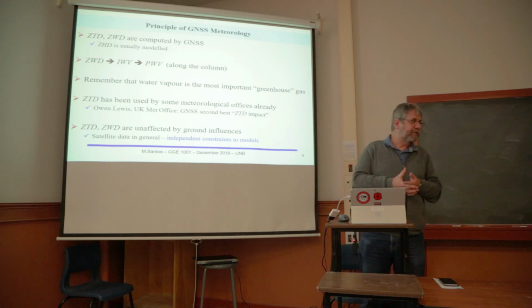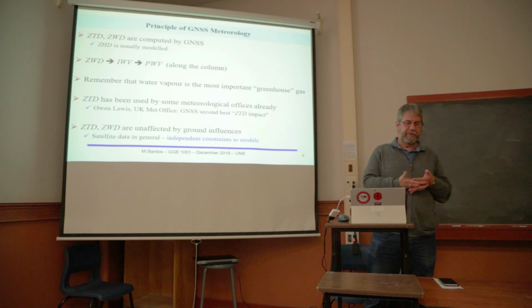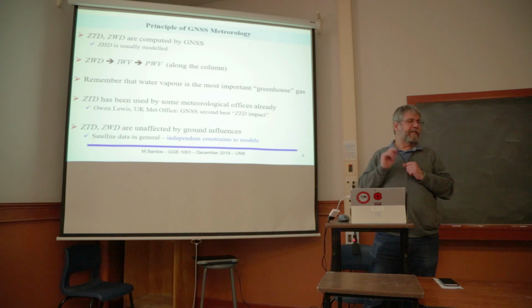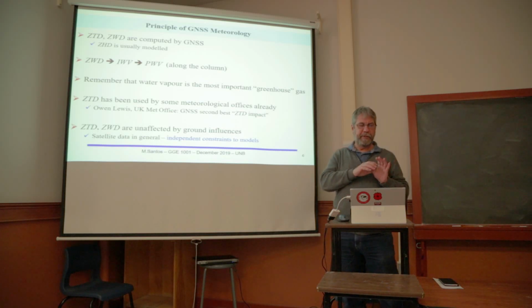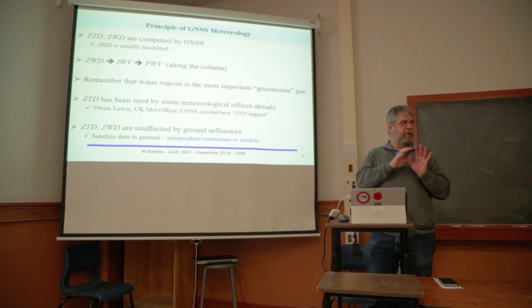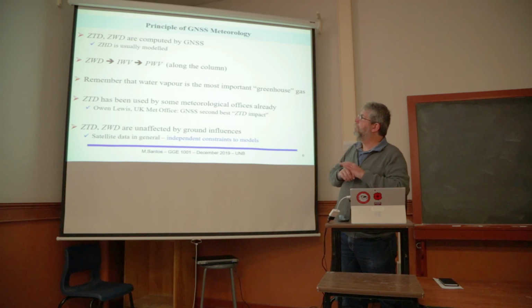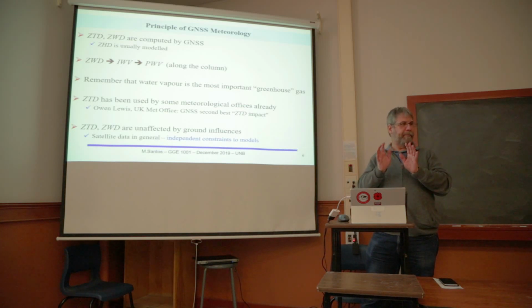ZHD, which is a function of pressure, is usually modeled. It's easier to model. And the interesting thing is that the zenith wet delay, which contains the moisture, we can use that to compute the so-called PWV, which is precipitable water vapor.